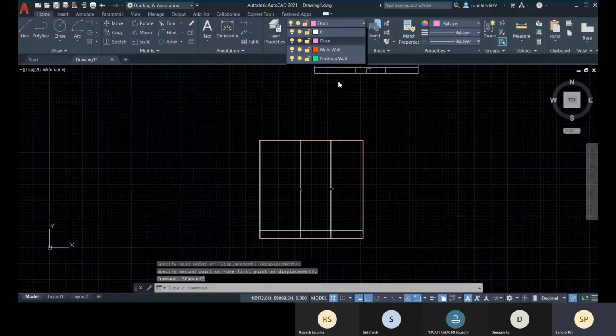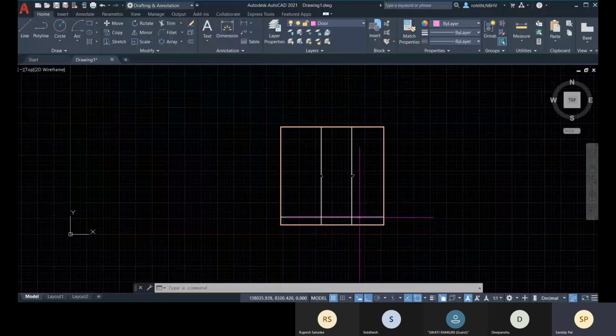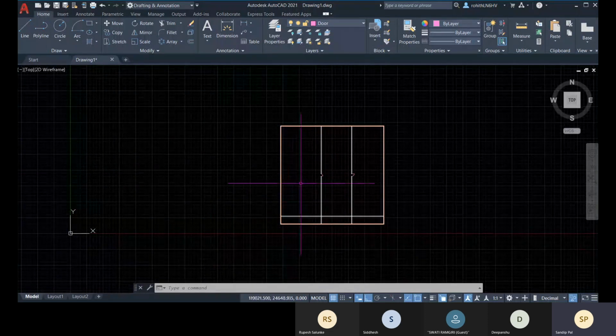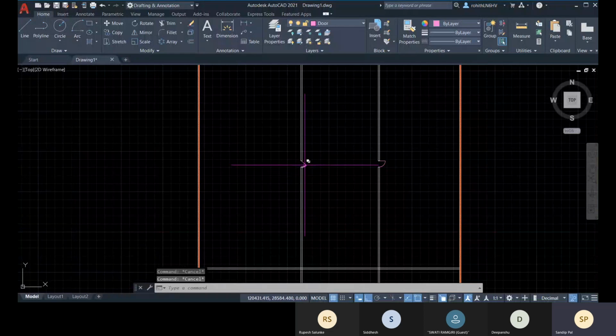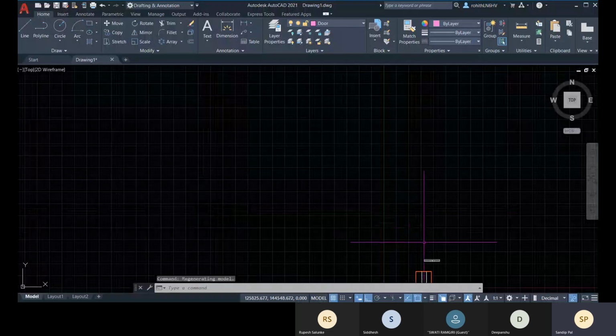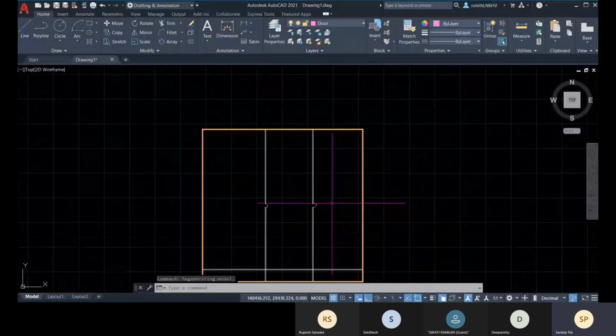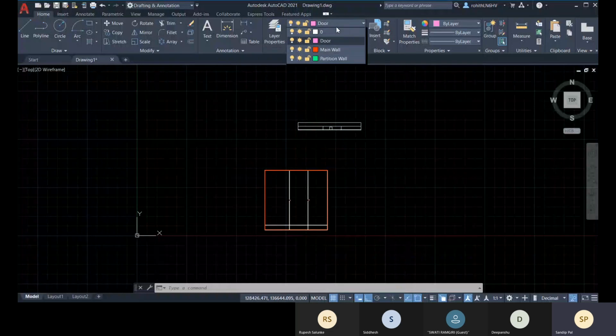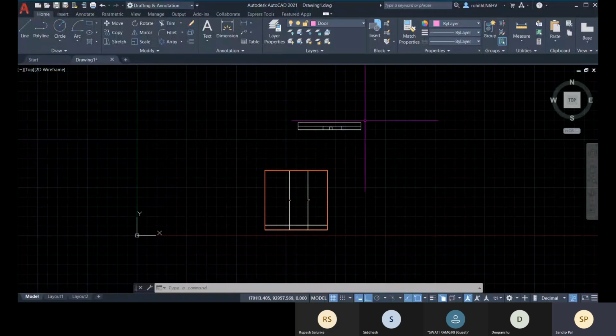Okay, so when you use this freeze option, when you have a lot of objects within your project, and you want to select some objects, you want to know how many doors are there. There is so big a project that finding out all the doors is not possible like this. Finding it out this way may take a lot of time. So for that, what you can do, you can simply freeze all the layers and just press Control A. Those objects which are present within this AutoCAD will be selected only. And after that, it will be easier for you to identify how many objects are there.